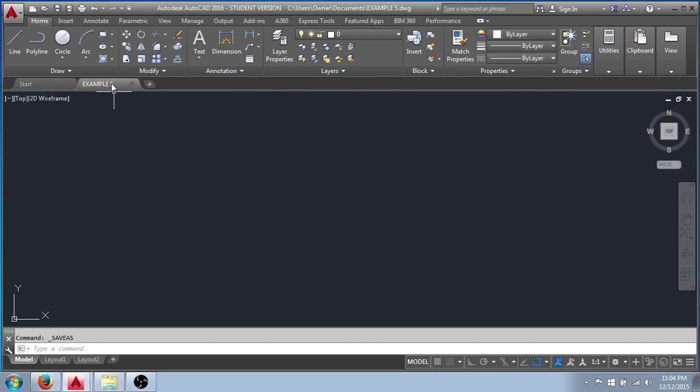What you'll see now is my Drawing tab now shows the name that I gave my file, Example 5, and this is also reflected up in our address bar with Example 5.dwg. So one of the key important things of doing the Save As right away before we start drawing is that once we've done that, it allows us to do periodic saves, meaning saving our work back to the drawing file so that we don't lose our work, say in case your computer crashes or something like that.